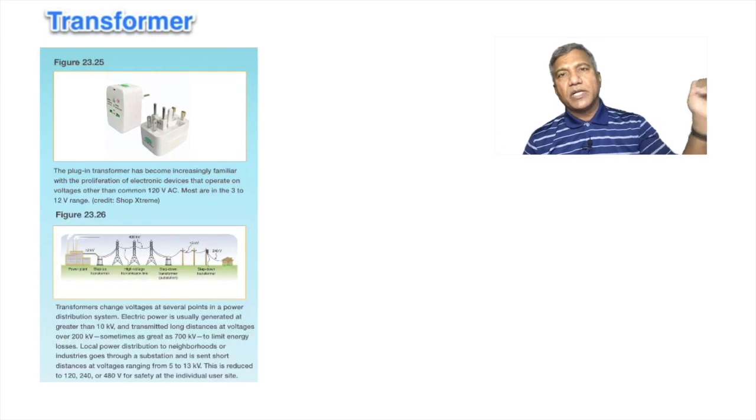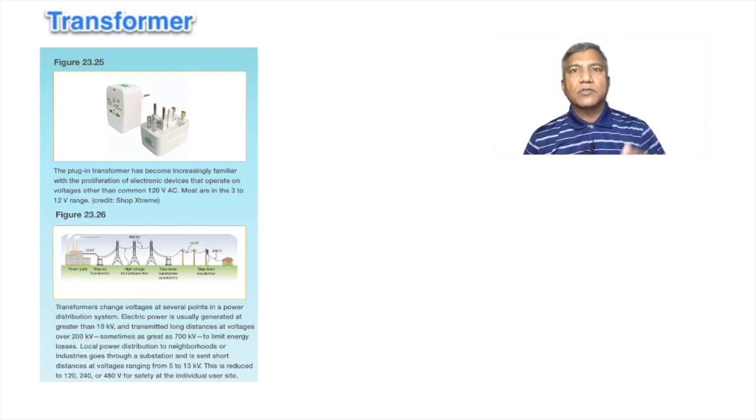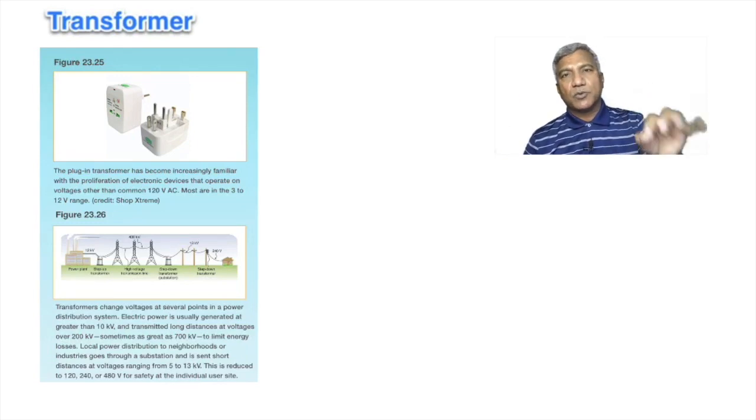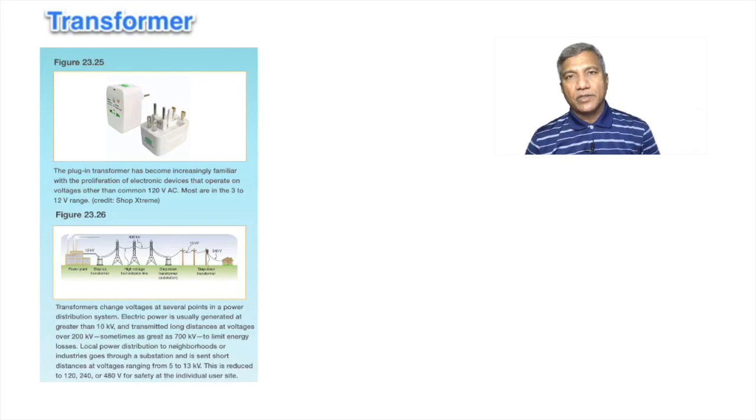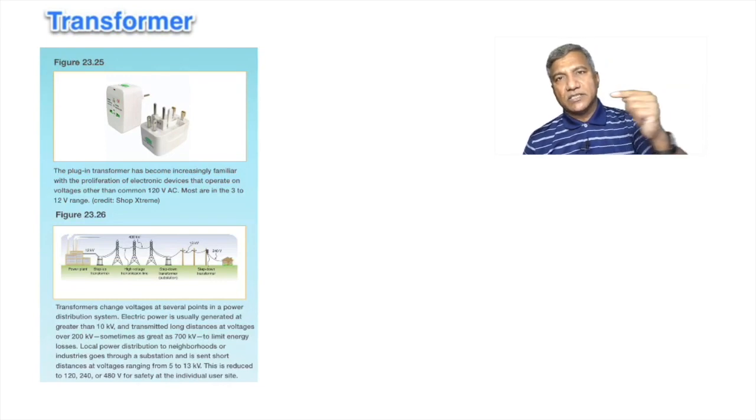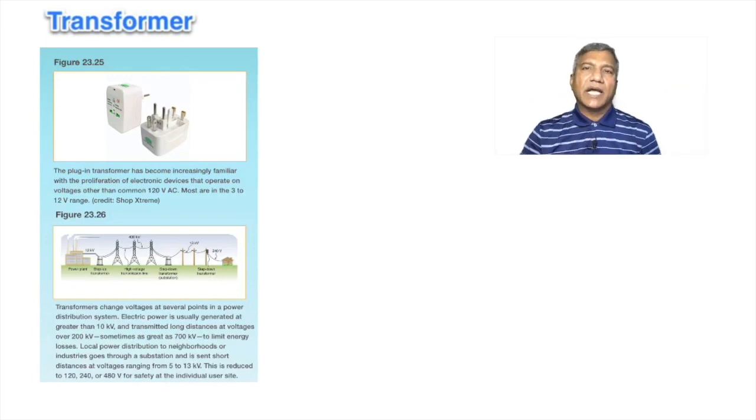While we're bringing that current through the cables, there's going to be a lot of heat produced, and so a lot of wastage. The heat produced depends on the square of the current. So in order to produce a smaller amount of heat and less wastage, the current has to be really small.